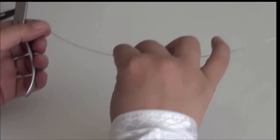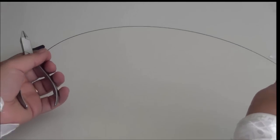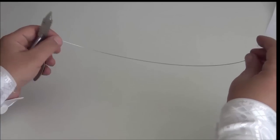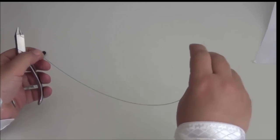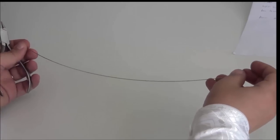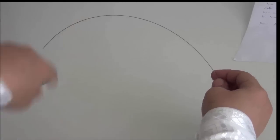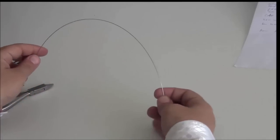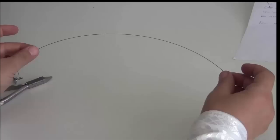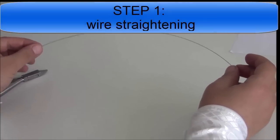So we're going to use this wire and we're going to go through now the steps of how to bend wires. And to bend wires we need to learn the basic skills of wire bending, and this is the subject of this lab. It's only basic skills of wire bending. So if I receive a wire, naturally this wire comes in loops because it comes stored in that way. So you will have it with a curve, but before beginning any work with wires we should straighten them.